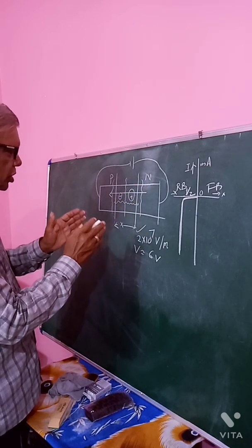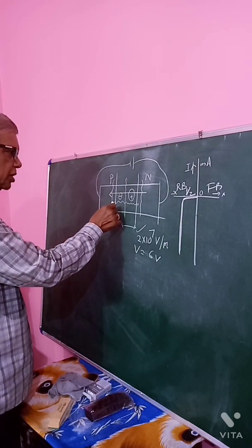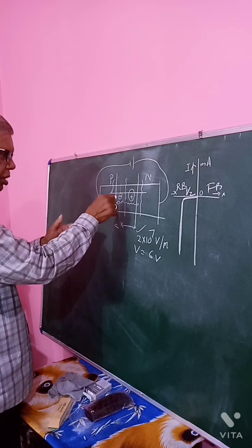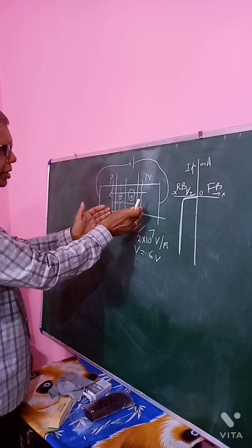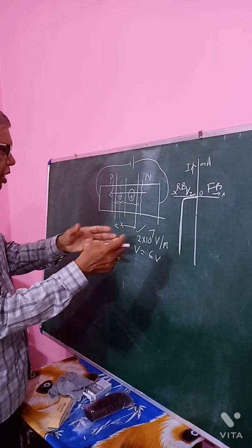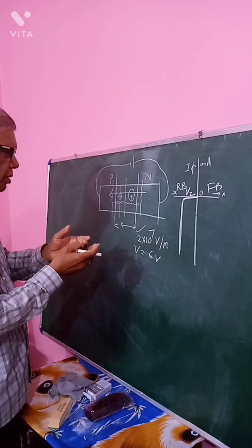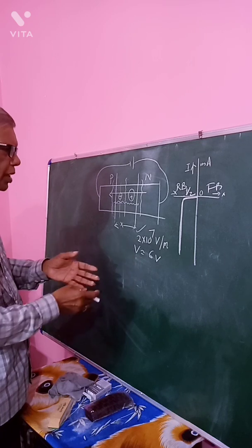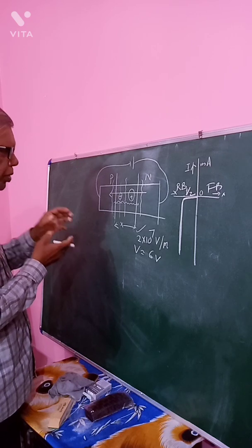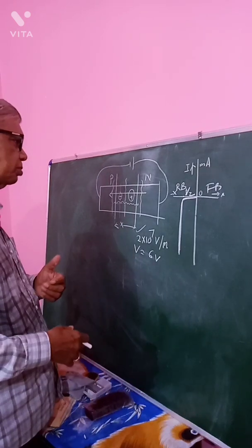Now, under such circumstances, the electrons, the minority carriers from the P region, move towards the N region, and while in motion it gains energy because the depletion width is wide. It gains energy and due to collision, knocks out electrons, producing more and more electrons, and the process builds up, continues, and suddenly there is a large amount of electrons moving towards the N region and finally swept out by the positive terminal of the battery.